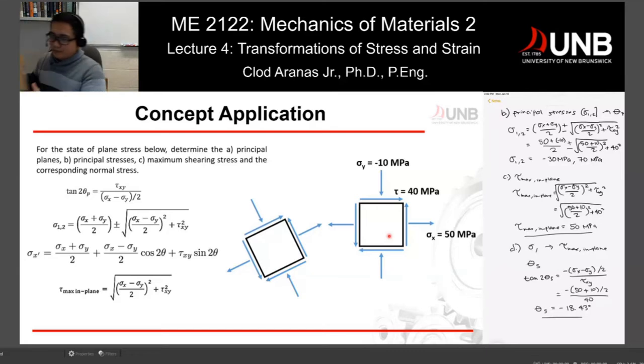So this would mean that if we go back to this problem, just imagine I have a box here that refers to elements. Let's say those stresses are applied to horizontal and perpendicular lines. So I will rotate it. I'm just checking which one is clockwise on your end. I cannot figure out which rotation, but anyway, in order for you to get your principal stresses, you have to rotate counterclockwise. And if you go back to your zero position, in order to get your maximum shear stress, you have to rotate clockwise because it's negative. That would be the condition wherein you will get your maximum shear stress.